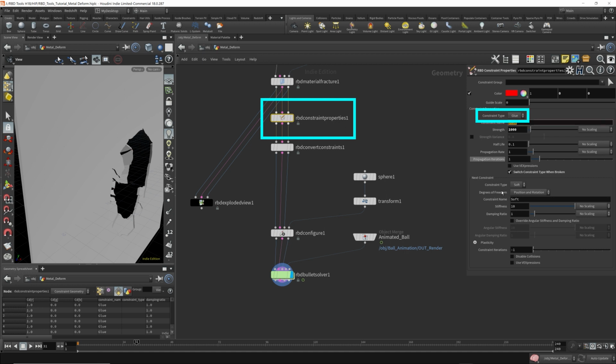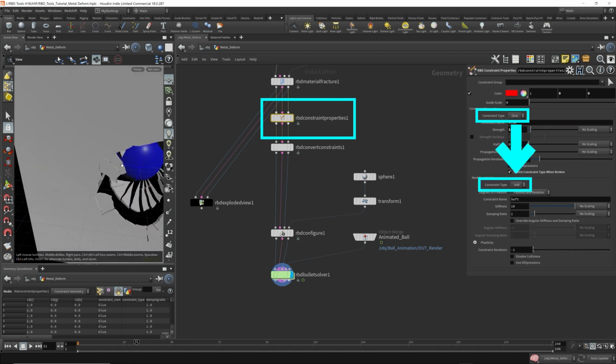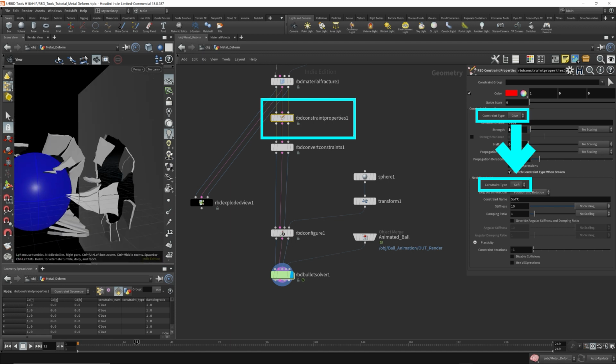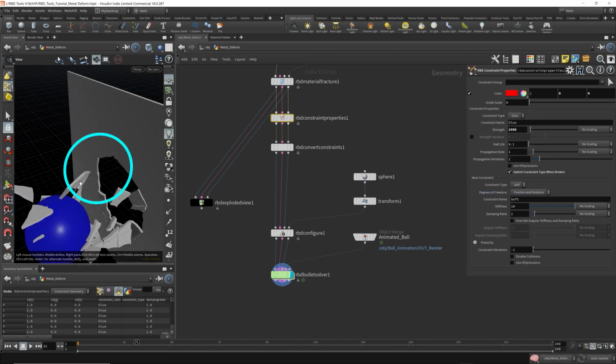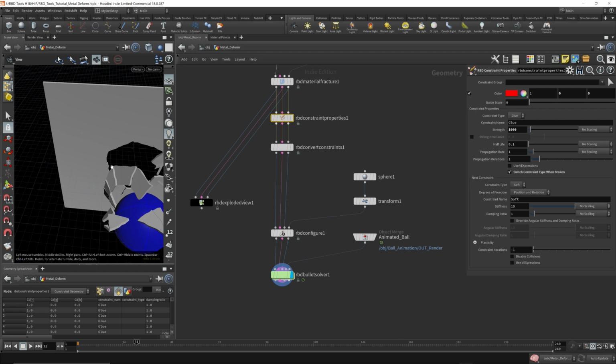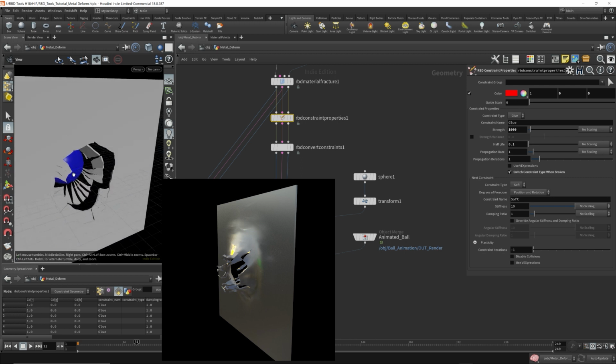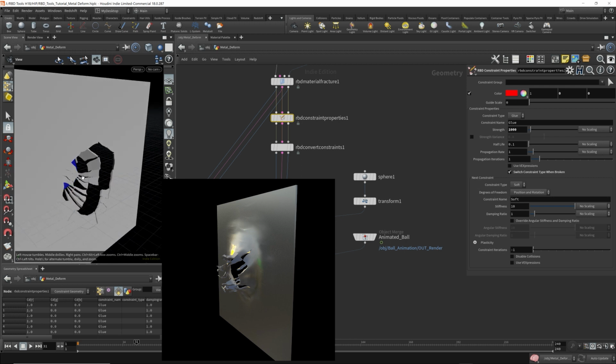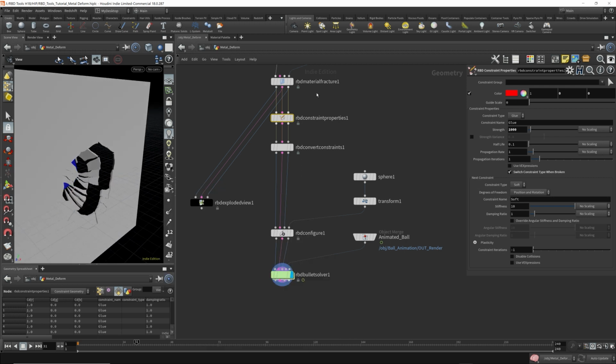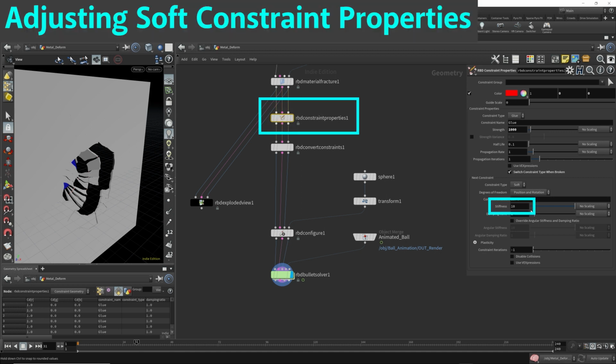So it's being shifted from a glue to a soft constraint. So it's being held together in some parts. Unfortunately, this wasn't held together with this. I kind of wanted this piece to stick here and then to stay in place. So this would end up like a tearing, like the ball tears through a hole through the metal. That's what I want. Now, in order to achieve that, the first thing is the stiffness.